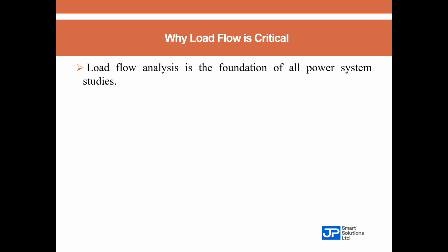For example, short circuit analysis requires the operating condition from a load flow analysis. Protection coordination is influenced by load flow results. Optimization studies begin with load flow studies.